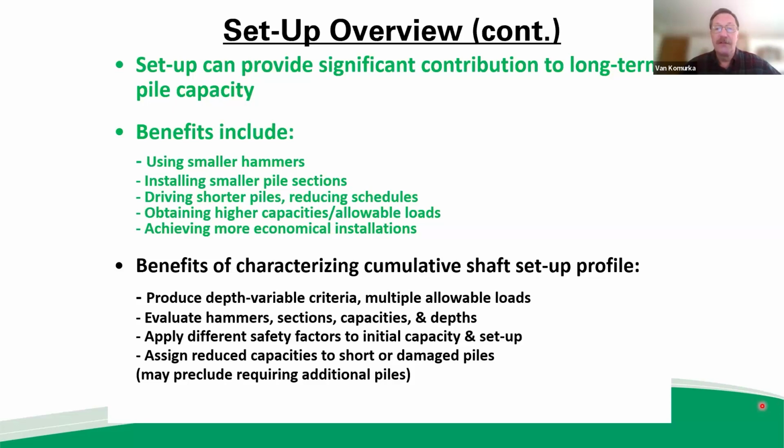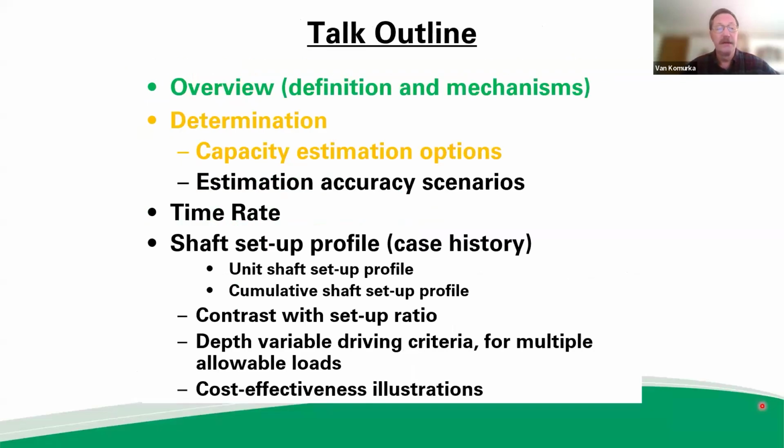One of the benefits of this approach is that you can apply different safety factors to the initial capacity and to setup, and we'll talk about that a little more. And it allows you the flexibility to assign reduced capacities to piles that stop short or get damaged, and we'll see the effect of that. As well, as it says here, it may mean that you don't have to drive additional piles for replacement.